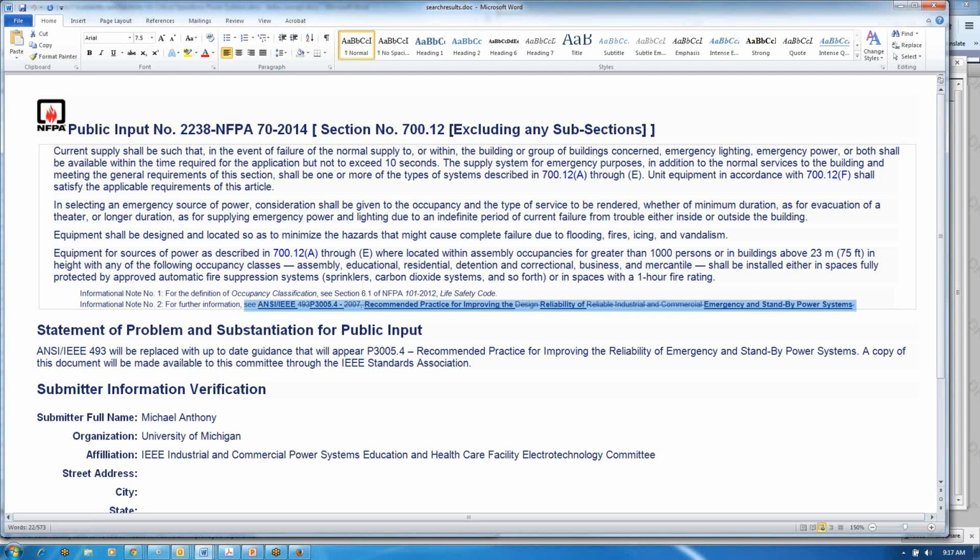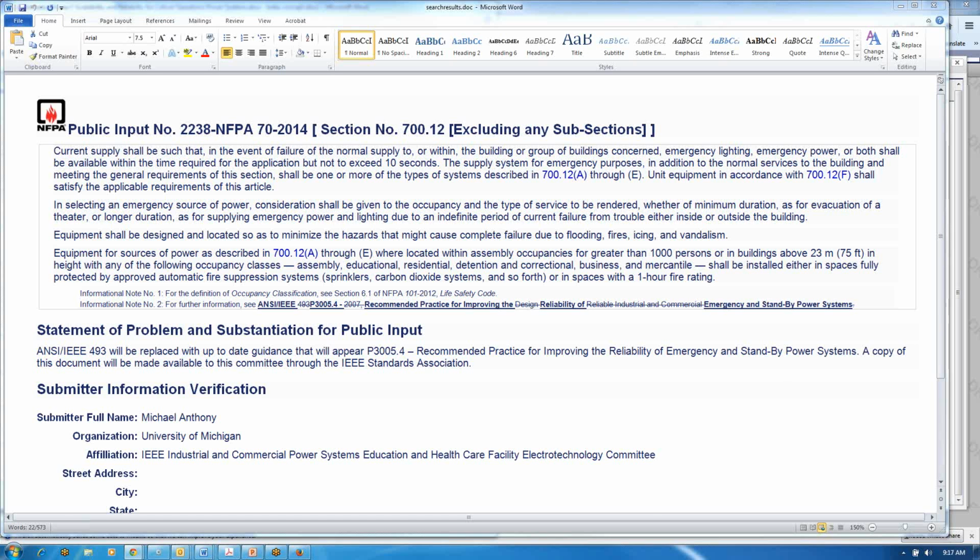And in many cases, and I'll preface this with a statement that in looking at data center applications, it's infrequent that the addition of a second utility feed produces a substantial improvement or reduction in unreliability. And examining why that is the case requires a careful sifting through the output of the fault tree analysis.